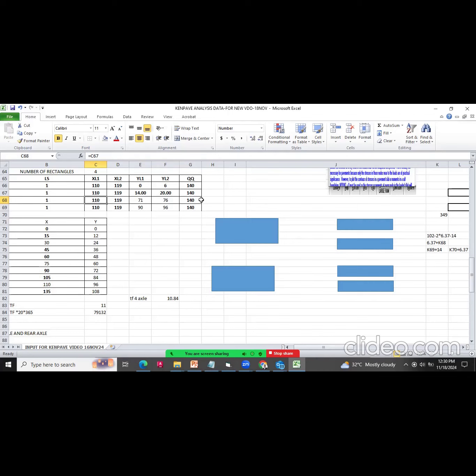In a rigid pavement slab, we have to make the grids, and for that we have to define the grid size. Mind you, the ratio between the x-axis and y-axis should not be more than 2. Maybe 2.5 is sometimes enough, but it doesn't take more than 3, and sometimes the limit is actually 5, but try to have the square grid as close as possible.